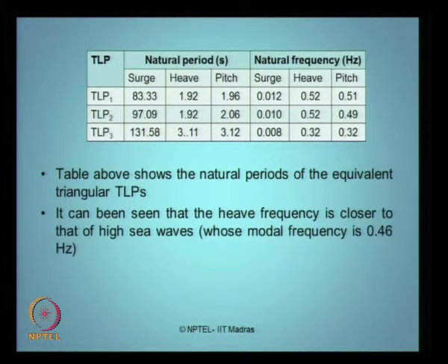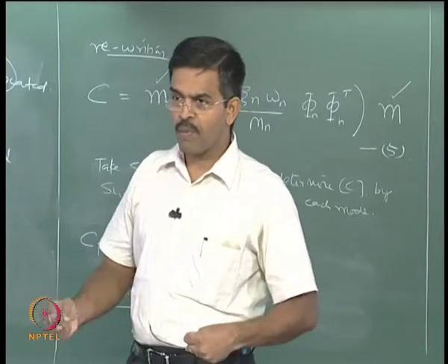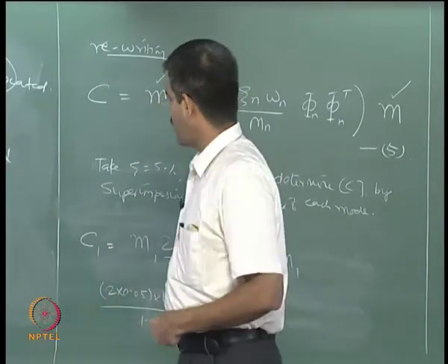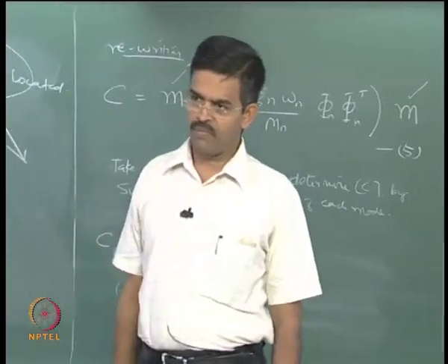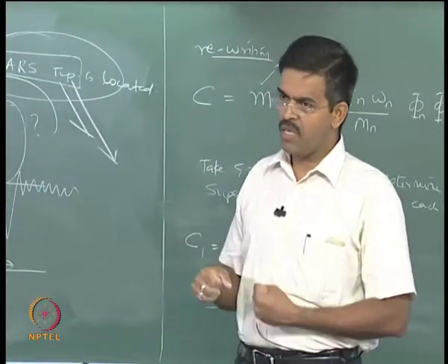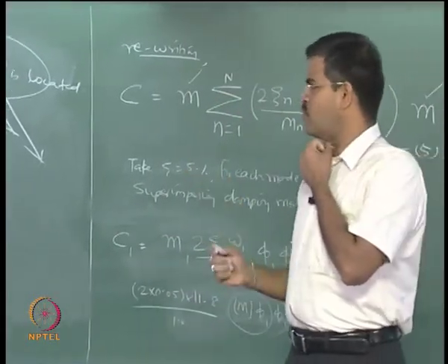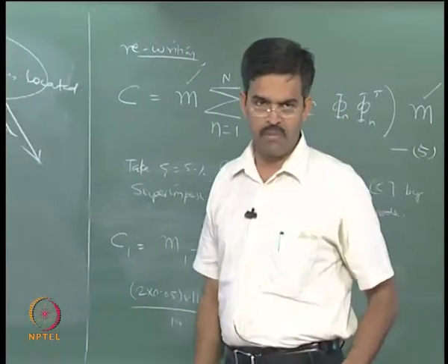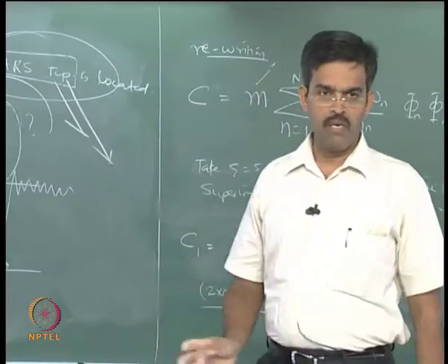Now, interestingly you see that the heave frequency in this particular case is closer to the modal frequency of 0.46 that you have used in the PM spectrum. So, I am trying to look at the near resonance case in the stiff degree of platform and look whether the platform gets completely uprooted in case of such waves coming and attacking the platform, because uprooting will happen only when the heave motion is phenomenally high. Okay. So, 0.46 is the modal frequency I have used in my PM spectrum, in the last slide we showed that, and 0.52 is my heave frequency.